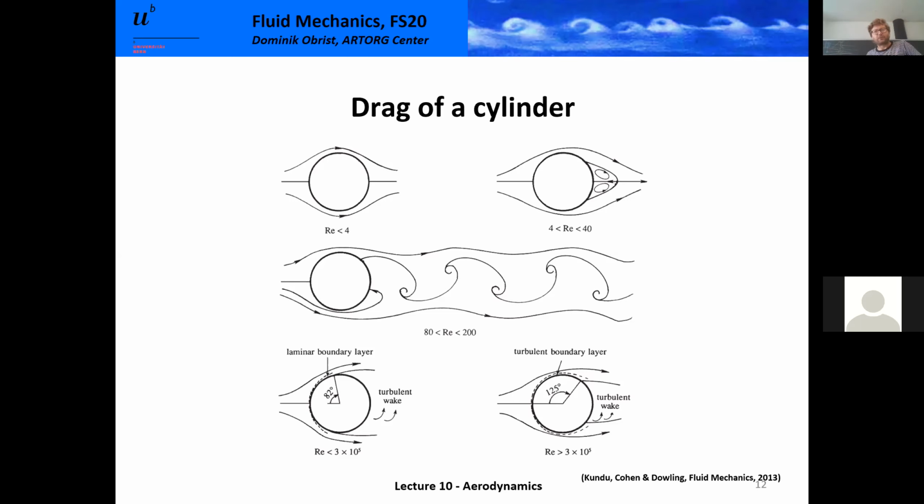You also see this from the fuller, bigger belly of the velocity profile. There's more energy in it, so it has a tendency to remain attached longer. It takes more to detach it from the surface. So this is a general phenomenon: turbulent boundary layers are more energetic, stay longer on the surface, and separate later.